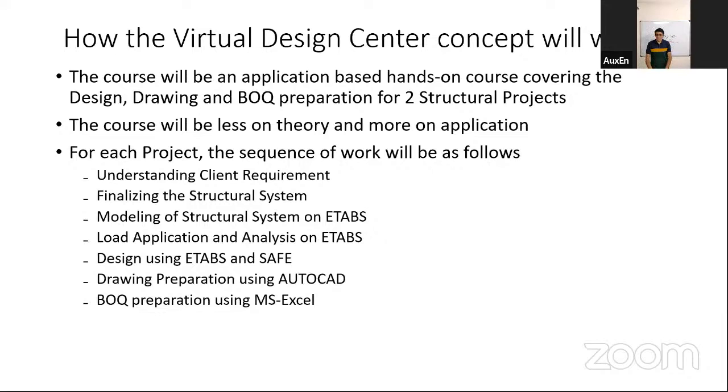Then that structural system we will model in ETABS. Once we model that structural system in ETABS, then we will move to load application. Whatever load we need to apply as per the relevant Indian standards, that we will apply. Then we will analyze our structure on ETABS. Once our structure has been analyzed, then we will be designing our structure on ETABS.